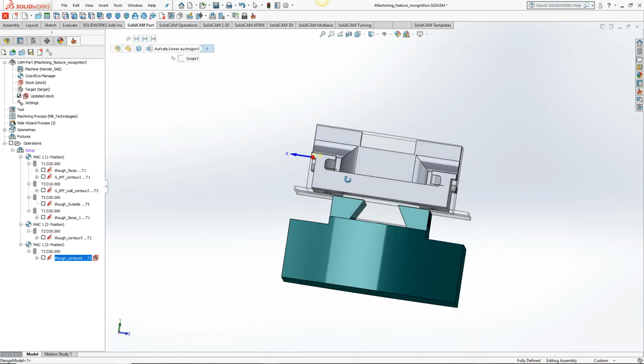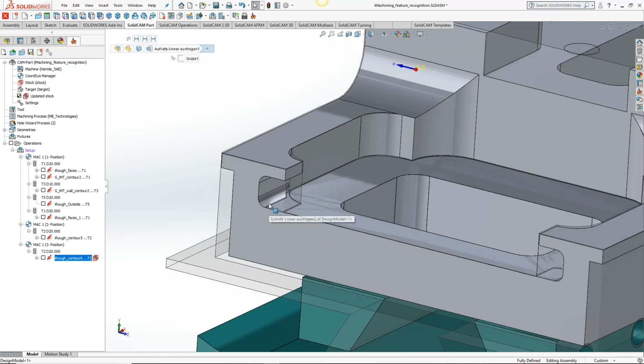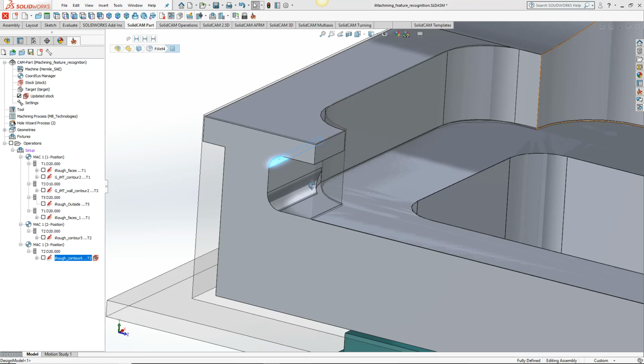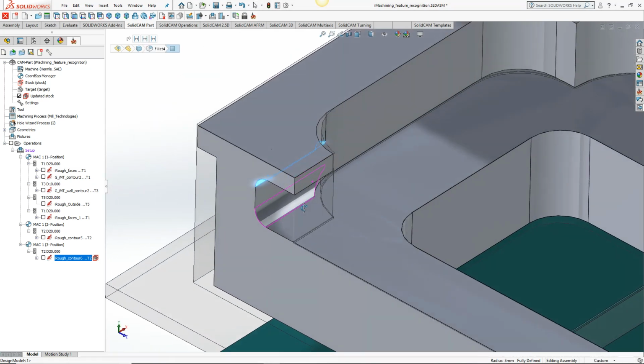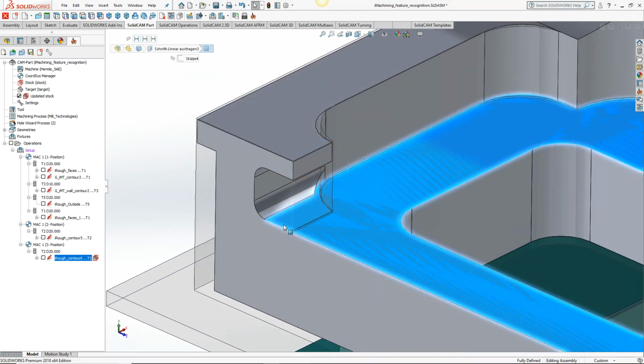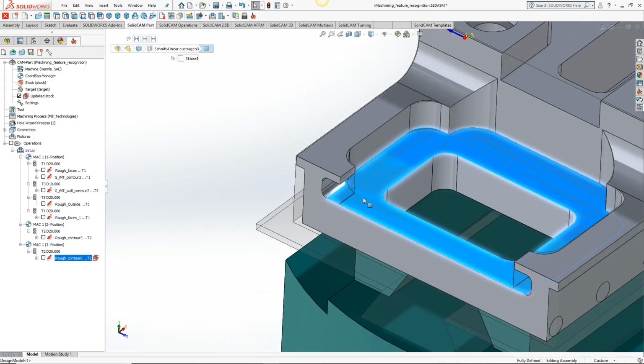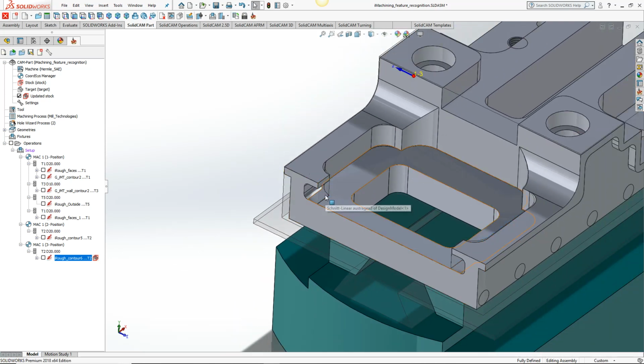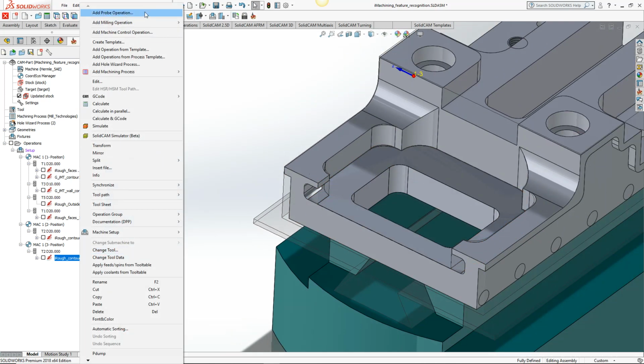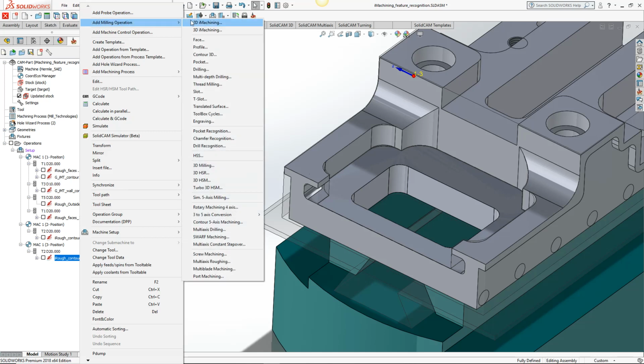Now that we've machined that, we have these little undercuts we have to deal with that we saw from the first operation. It did its machinable feature modification, and even though we selected these faces, it was smart enough to see that we had that undercut. But now we need to cut these 2 little features out. We will make another 2D iMachining operation.